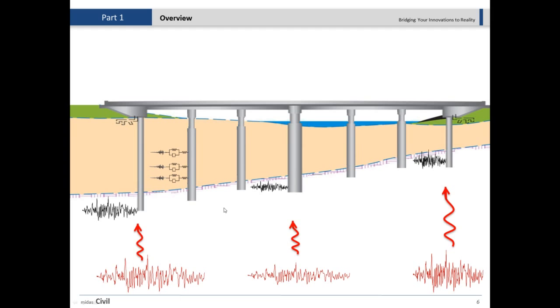All right, and the next part is that those forces are going to shake the structure, and after the structure is shaken, the structure gives us a response. That response means the displacement and deformation of different parts. It could be internal forces like moment, shear, and axial forces. Those are all considered the response of the structure based on the earthquake force that we applied on them. And once again, different parts of the ground or different parts of the bridge experience different forces.